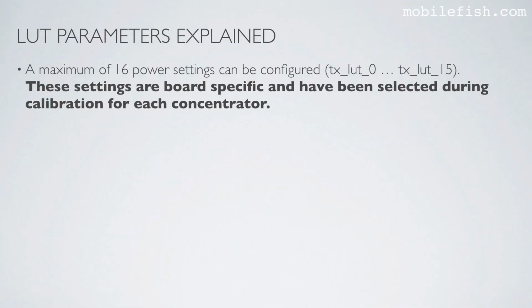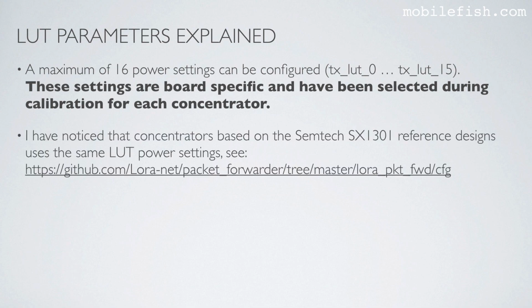As mentioned earlier, a maximum of 16 power settings can be configured. These settings are board specific and have been selected during calibration for each concentrator. I have noticed that concentrators based on the Semtech SX1301 reference designs use the same lookup table power settings. See this link.